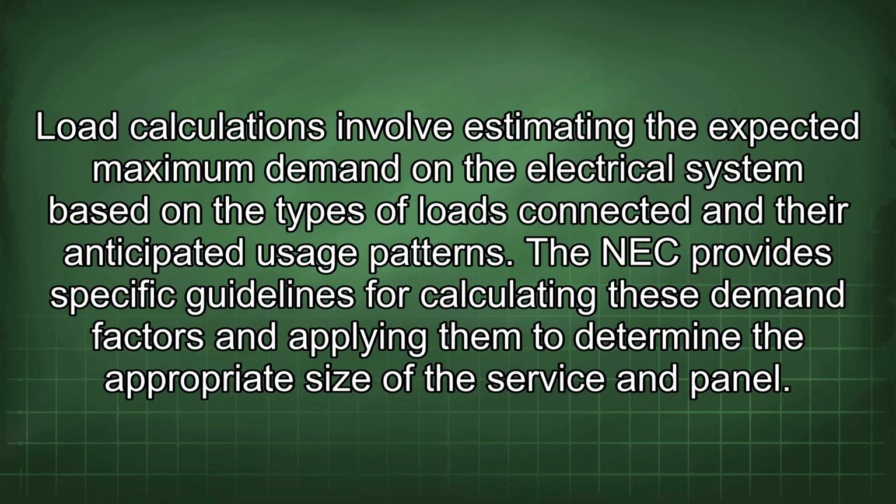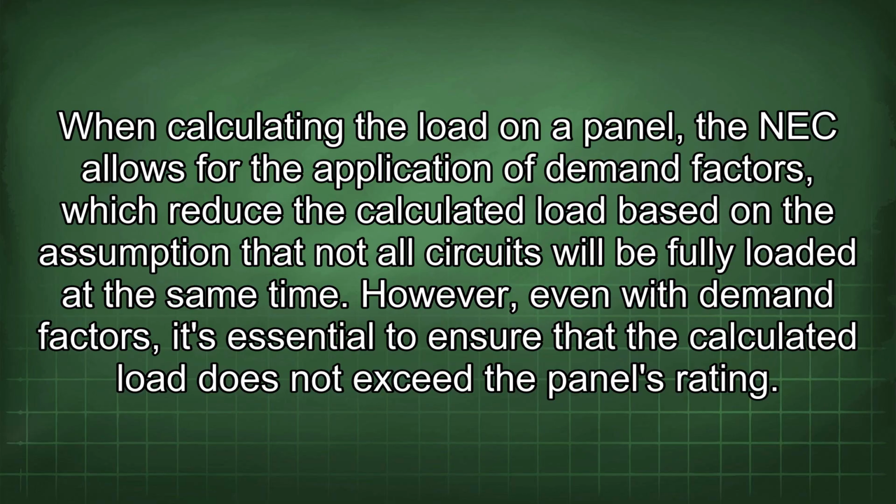The NEC provides specific guidelines for calculating these demand factors and applying them to determine the appropriate size of the service and panel. When calculating the load on a panel, the NEC allows for the application of demand factors, which reduce the calculated load based on the assumption that not all circuits will be fully loaded at the same time. However, even with demand factors, it's essential to ensure that the calculated load does not exceed the panel's rating.